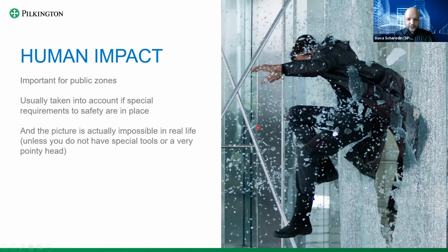Which norm standards are you using for calculating wind loads? That is highly dependent on which country we are doing the calculation for. We are always trying to use local norms. For Russia and many former USSR countries, we are using GOST and SNiP norms.